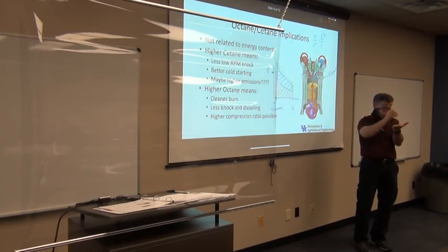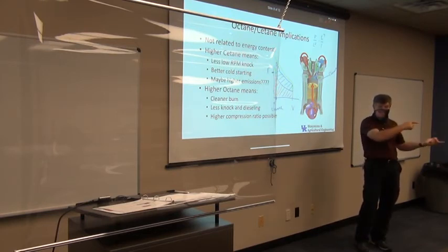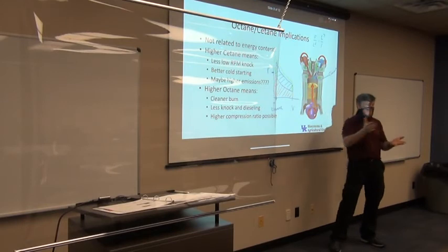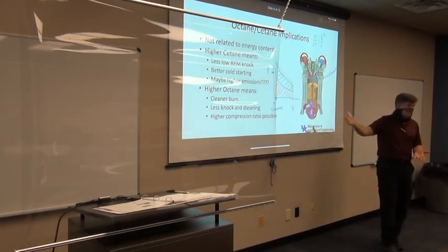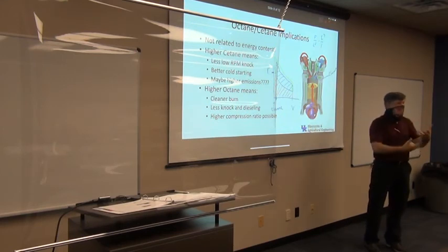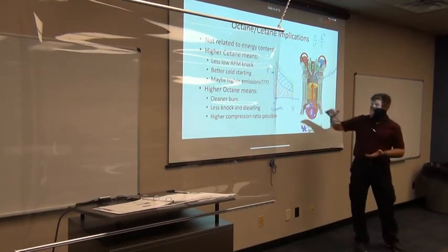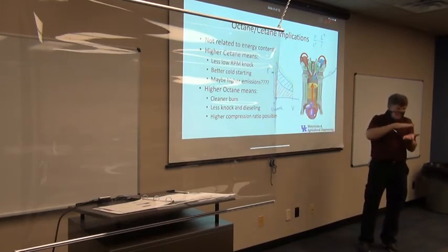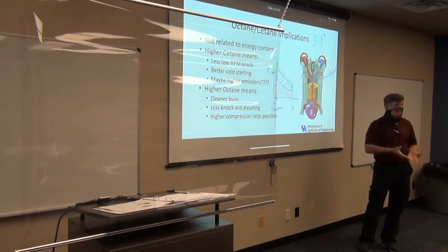So what will happen is that fuel can burn too fast before it mixes with the oxygen, and just like we talked about a few minutes ago, if it's not getting that oxygen available, that's when I'm ending up with carbon monoxide, free carbon, and other stuff coming out because it can't fully combust. It can't execute that combustion process in there. So sometimes the higher cetane, the lower auto ignition pressure can actually hurt us a little bit because it burns too quick. I need it to mix completely before it burns all the way through. Making sense? So it's a complicated deal.